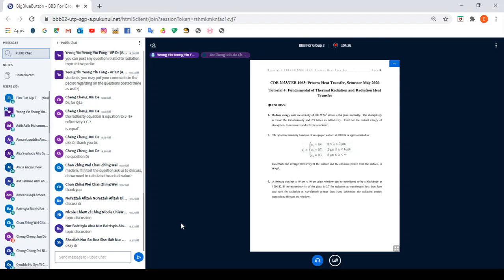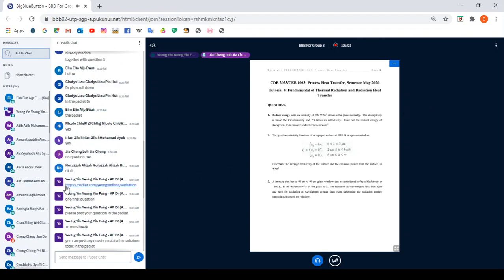Okay, doctor. For 10D, it means 10 times the diameter of the pipe. For example, if the diameter is 0.01, after you multiply, you get LT as 0.1. That means beyond 0.1, the flow is all fully developed. Yes, all fully developed. Oh, okay.